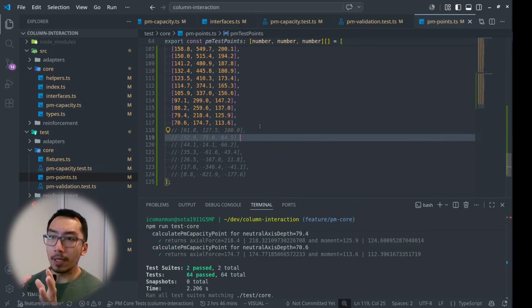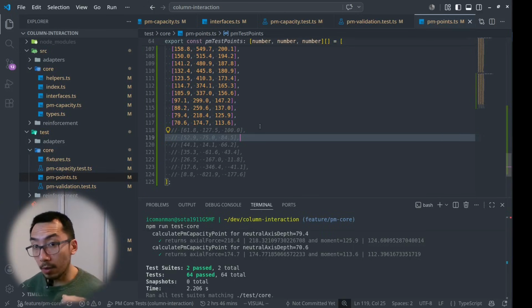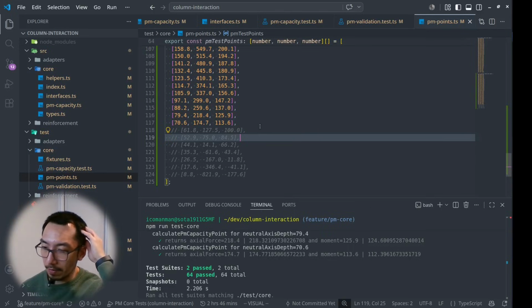So this particular converted capability is not capable. What an irony, right? It is not capable of dealing with another layer of tension steel, let's just say. Because at that point, when we cross the neutral axis, our assumed compression steel would turn into tension, if it's even workable.